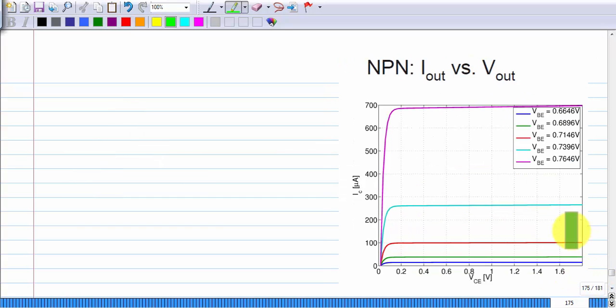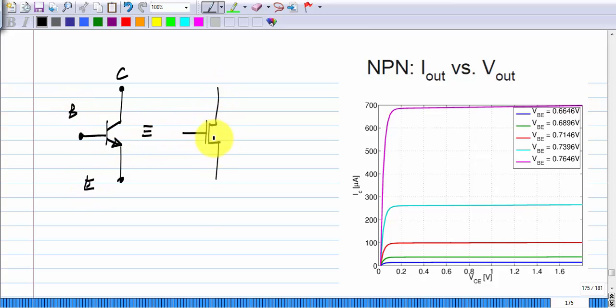Now here we have another device which is known as an NPN transistor, which we will discuss later in the course. This was the type of semiconductor transistor that came after the vacuum tubes. It displaced the vacuum tubes, and it was itself kind of displaced by the MOS transistor for many applications. These are still being used, but the MOS is more popular. Okay, so this has 3 terminals, collector, base and emitter, which correspond to respectively the drain, gate and the source. And you can see the characteristics are similar.